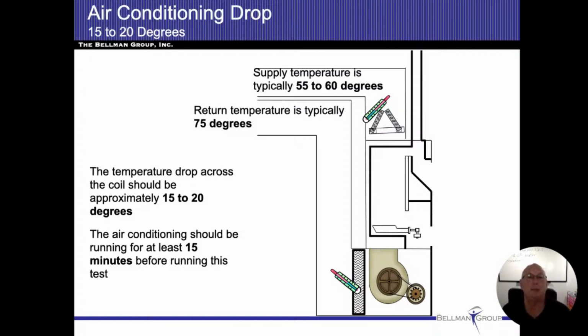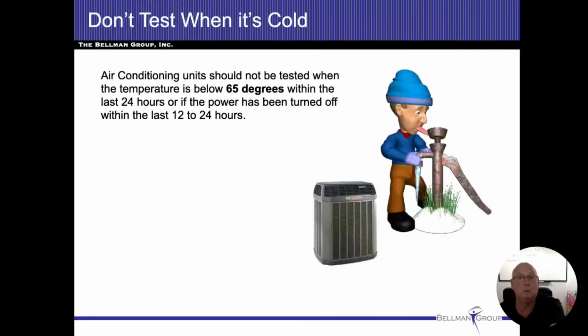It's saying that temperature because it's using the return as saying that that's 75 degrees. But I don't know, I find that most people keep it somewhere around 70 degrees. So whatever temperature it is coming in, we're looking for 15 to 20 degrees of a drop going out.